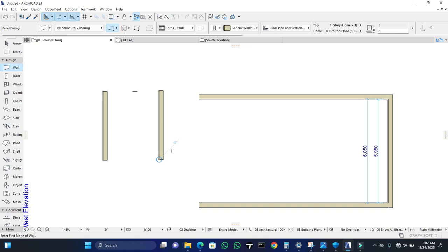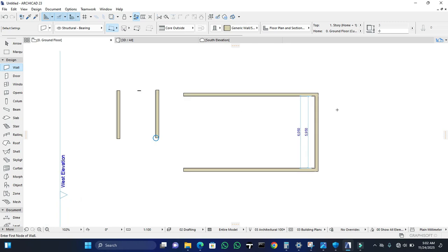This is because our working unit is set to meters now. Now say if I want to now draw a wall and I say, okay, let me type 4,000 millimeters, so that Archicad will know that, oh, I did not mean meters, so I mean millimeters, because of one reason or the other. And I type 4,000, just like this first one here. I type 4,000 and I press OK. Now this wall is going to be very long.